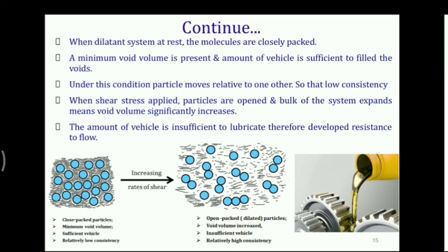So that's why in case of your dilatant system, as you shear your material, as you increase the rate of shear, the consistency of your material goes on increasing, the viscosity goes on increasing. That's why it is termed the shear thickening system.